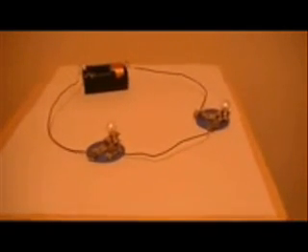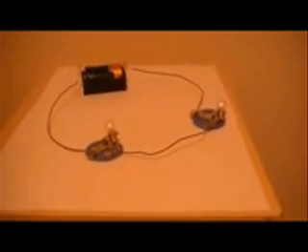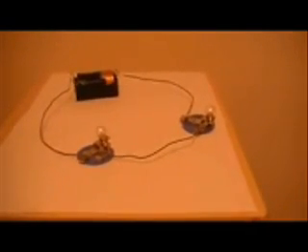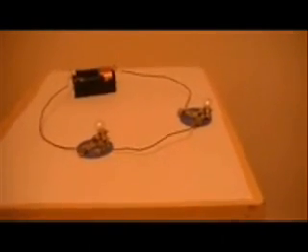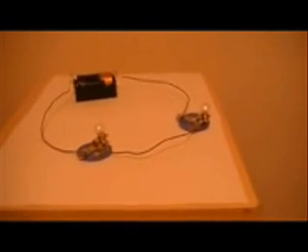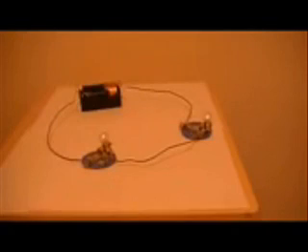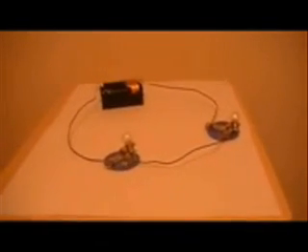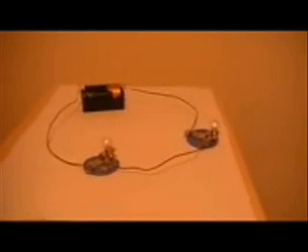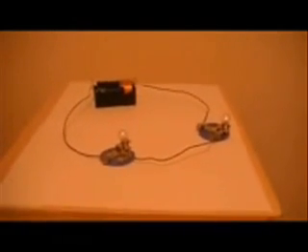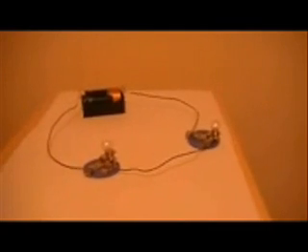What you can see here now is both bulbs are lighting, so it means our circuit is complete, is fully connected. But you may notice that the brightness of the two bulbs is the same for both bulbs, but not as bright as the bulb was in the first circuit we looked at. This is due to the fact that in a circuit that's in series, these two bulbs are getting the same current, the same amount of current as the bulb did on its own, but the voltage of the circuit has been split between the two.